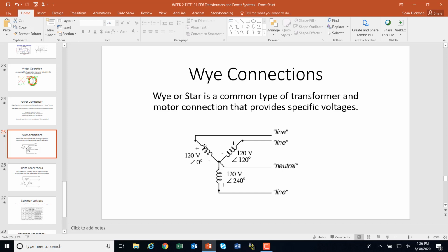So in this case, these coils are connected in a Y, and you can tell that this first coil right here ends up in series between this line and this line. Line 1 and 2, let's say, and then between line 1 and line 3, I've also got a series connection here, and I've also got then a final series connection between line 2 and line 3. So that's what we were talking about earlier. What happens when you put resistance in series? You're going to get more resistance, right? And then you're going to get less current flow. Okay.